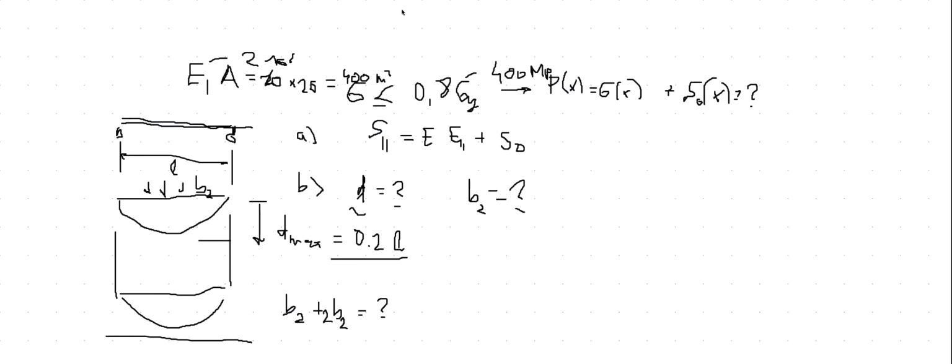So you can go through all these steps to get the second Piola-Kirchhoff stress. You can get this interpolation for deformation. You can obtain these elements. And please take, for example, what could be interesting is to take one 3-node element, so you have a better type of result with the shape functions that I just plotted in the previous discussion. This is 1/2 xi times (xi minus 1), then 1/2 xi times (xi plus 1) for the right-hand node, and then 1 minus xi squared for the one in the middle.